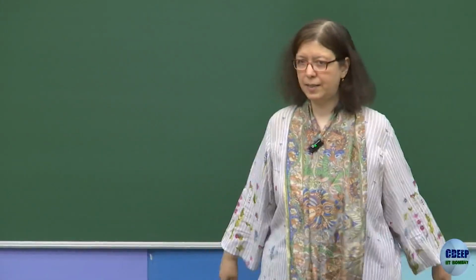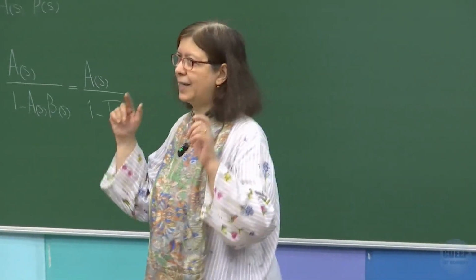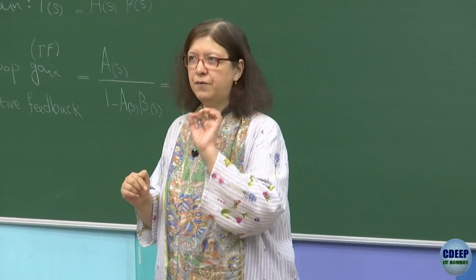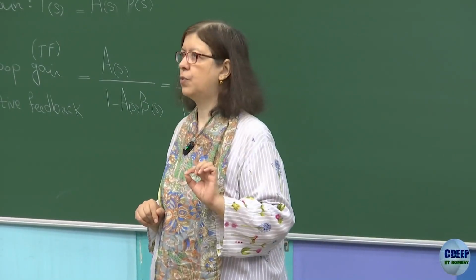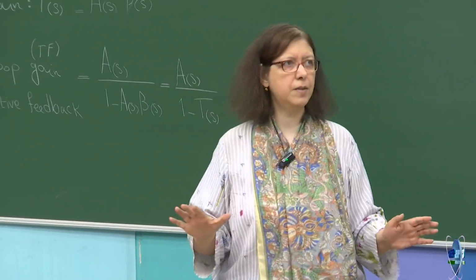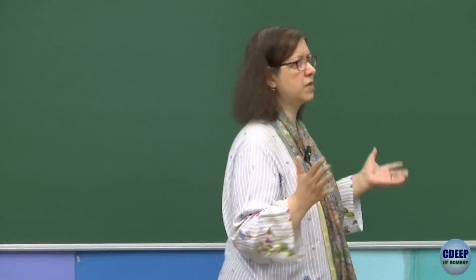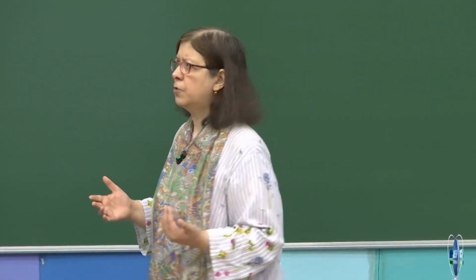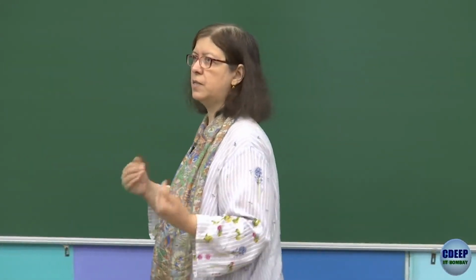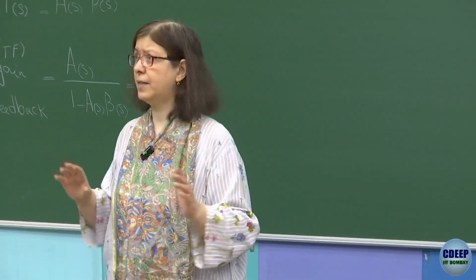If you have an ideal ADC and you apply the inputs in such a way that there will ideally be an equal number of occurrences for every possible code, from all zeros to all ones, we have an input which gets all values of analog voltage or analog current in the full scale range. Correspondingly, we generate codes. So you may have, for example, 1000 occurrences of a single code, and for all codes equally. Ideal case, it will happen that way.